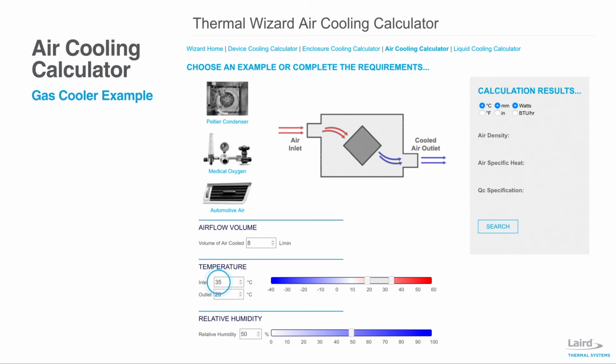While the maximum inlet temperature will be 43 degrees C, we will change the outlet temperature to 5 degrees C. We will leave the relative humidity at 50%. As we have been changing these specifications, the cooling requirements have been changing in the calculation results, where QC is now 5.6 watts. Click Search to see the results.